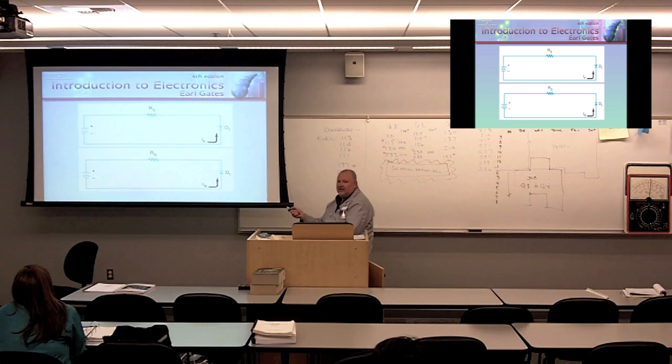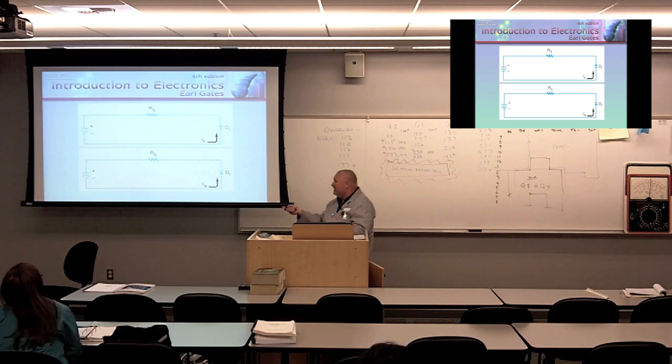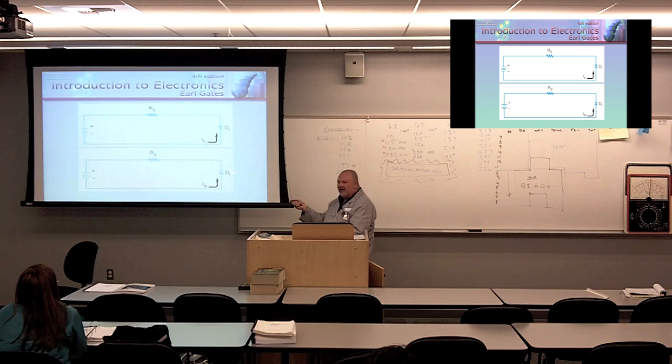Very good. What voltage will I get across my diode? What's that? 12 volts. Why? You will always read source voltage across an open. When this is reverse biased, this diode is going to act like an open. So 12 volts minus 12 volts gives me a remainder of 0 volts.